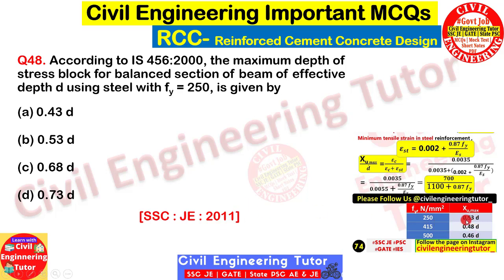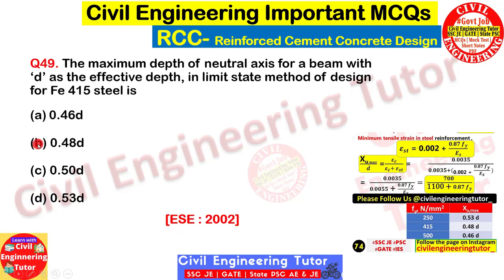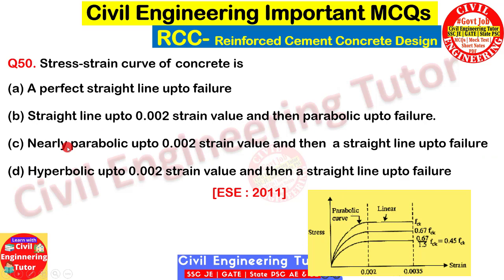So Xu max is 0.53D for 250. Here the grade is 250, and this was asked in SSC 2011. So the correct answer will be B. Now a similar type of question for Fe 415. The correct answer will be 0.48D. So here the answer will be B.